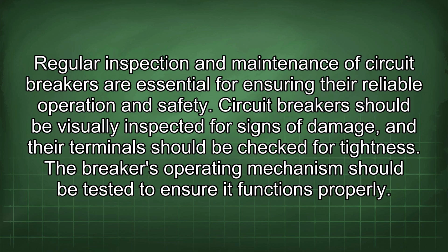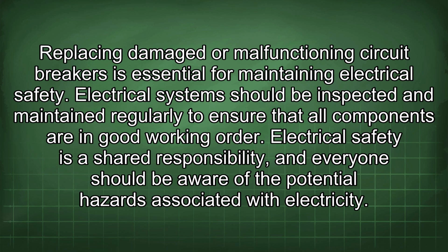Regular inspection and maintenance of circuit breakers are essential for ensuring their reliable operation and safety. Circuit breakers should be visually inspected for signs of damage, and their terminals should be checked for tightness. The breaker's operating mechanism should be tested to ensure it functions properly. Replacing damaged or malfunctioning circuit breakers is essential for maintaining electrical safety. The electrical system should be inspected and maintained regularly to ensure that all components are in good working order.